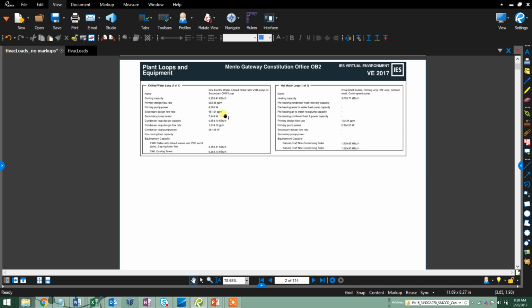But really what I'm looking for is trying to understand what is driving this 500 tons. What is the breakdown of the solar gains, the internal gains, and the ventilation air, and do those all make sense given my knowledge of a fairly glassy building and a fairly high load for an office space user?